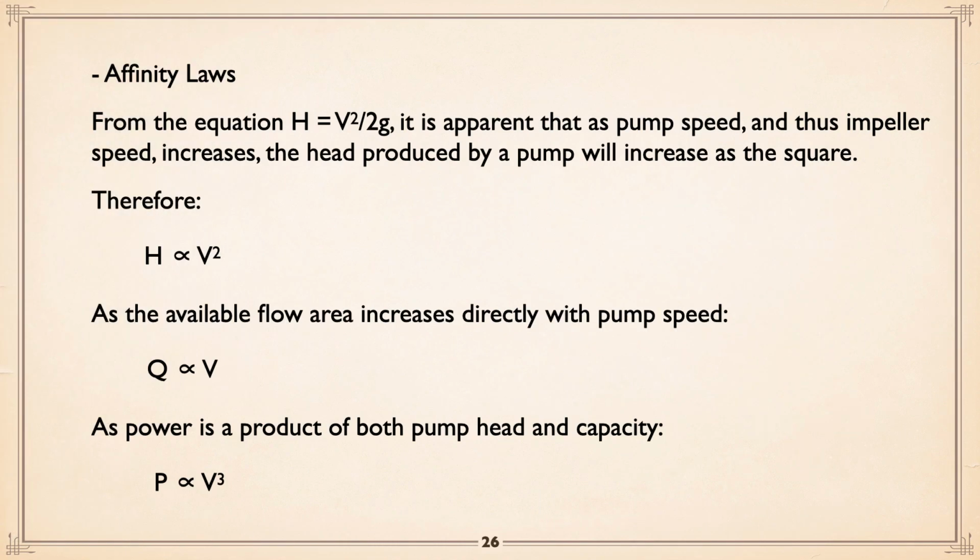Now, if you want to be a pump expert, you need to learn the affinity laws. They're very important. It basically comes from the fact that head varies as the square of pump speed, divided by 2g, gravity. Therefore, head varies as the square of speed. Double the speed, you get 4 times the head.